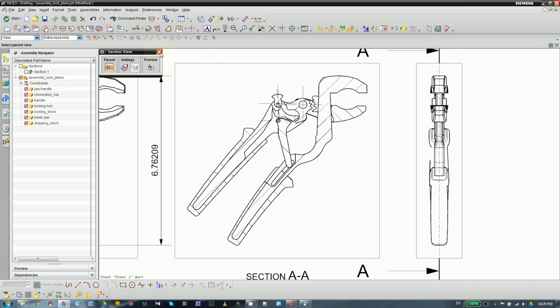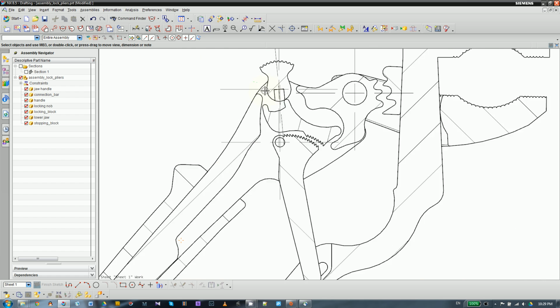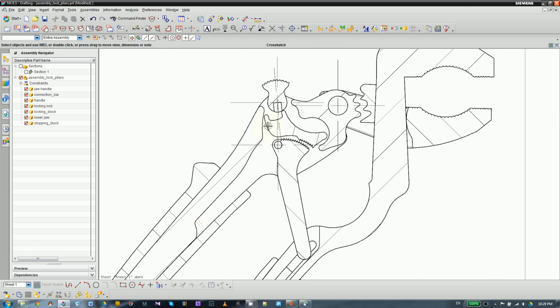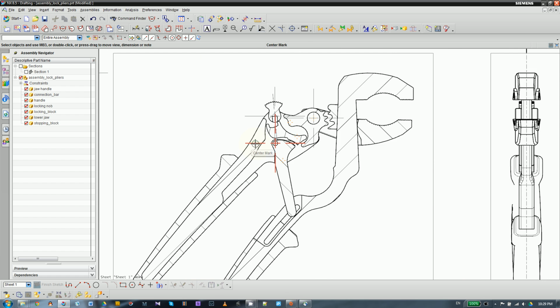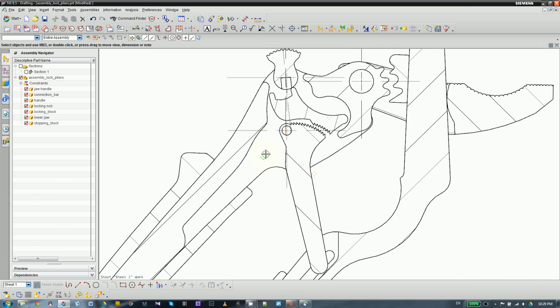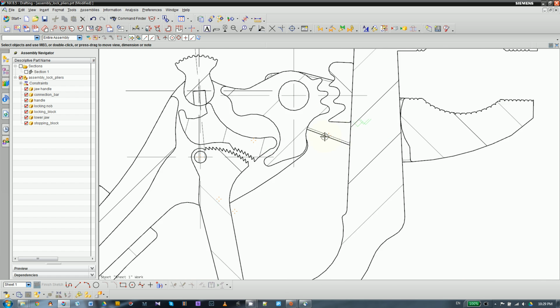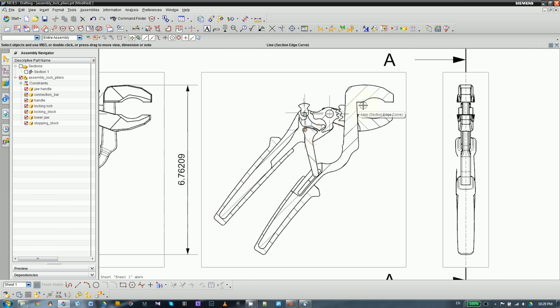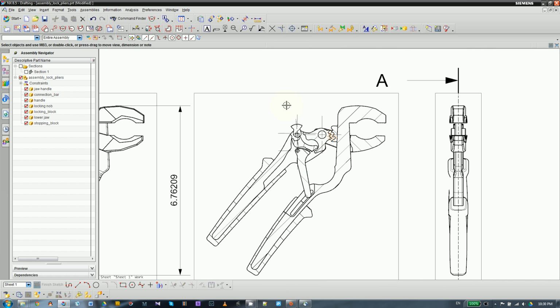So we have the cross section, and the crosshatch means that's the intersection of your assembly to the cutting plane. And what's that? That's behind your cutting plane. We can see those things, they are not on the cutting plane. Sometimes we want a very clear cross section without anything behind this cutting plane.